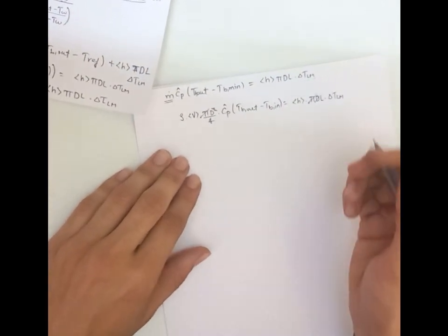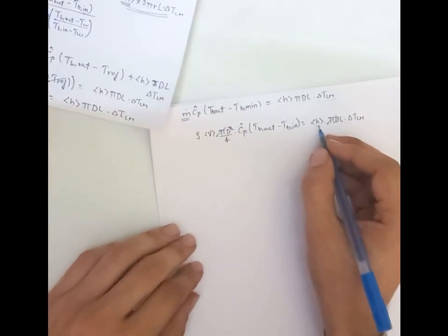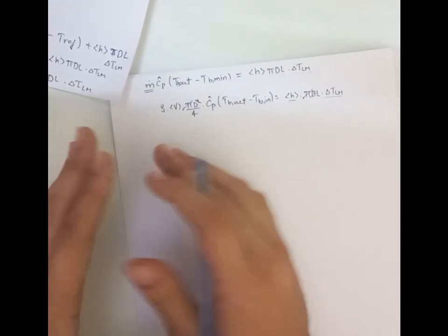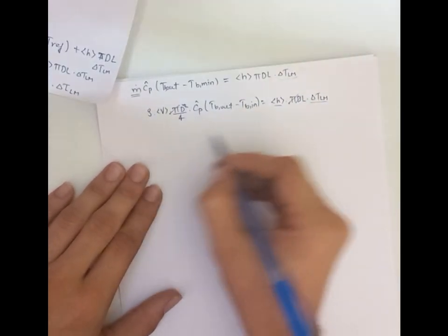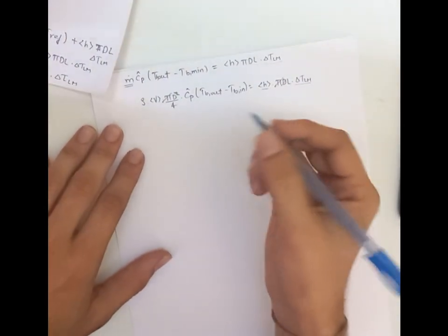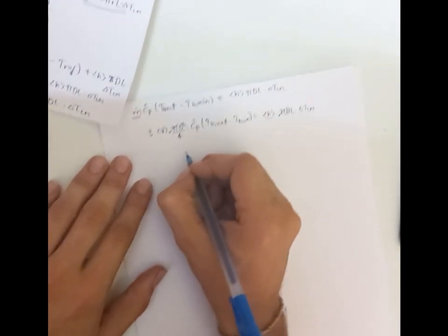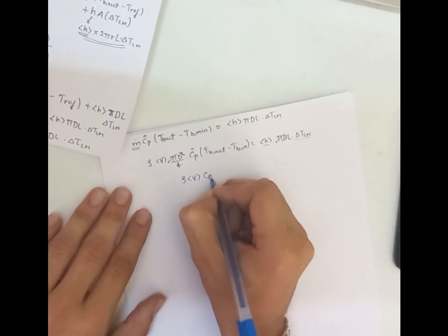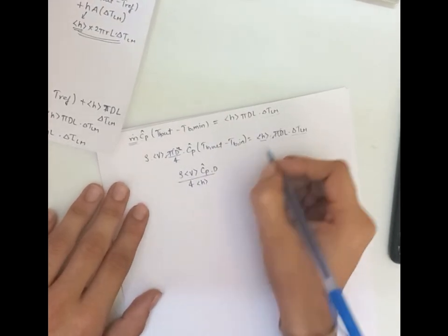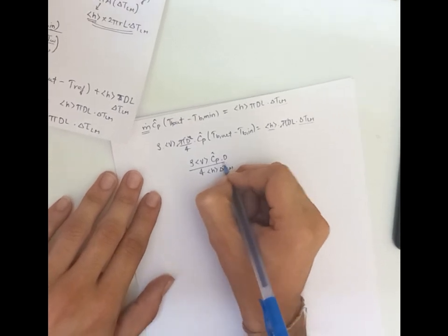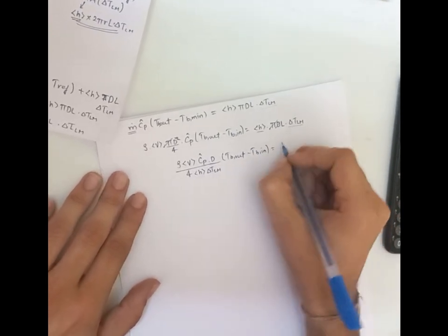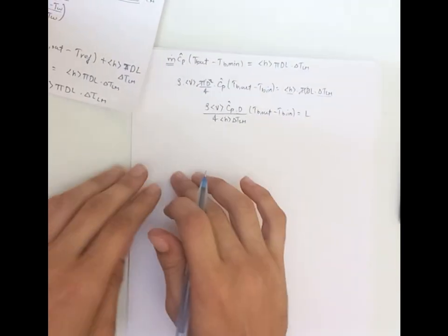So now what we're going to do is take out this h, the heat transfer coefficient, and this logarithmic mean to that side, so that we can equate L is equal to this whole term, because we need to find out L. So the whole term should be on the right hand side or left hand side, and we need to find out L. So we're going to write it as rho V Cp d by 4 h, the heat transfer coefficient, and delta TLM, the logarithmic mean temperature, and this is TB out minus TB in, is equal to L. So we can write it on that side, that will look better.